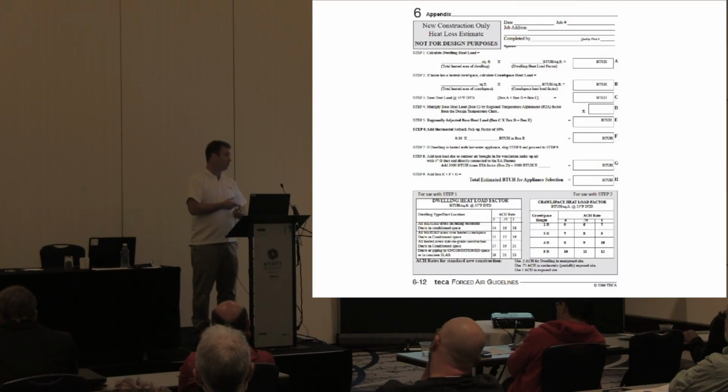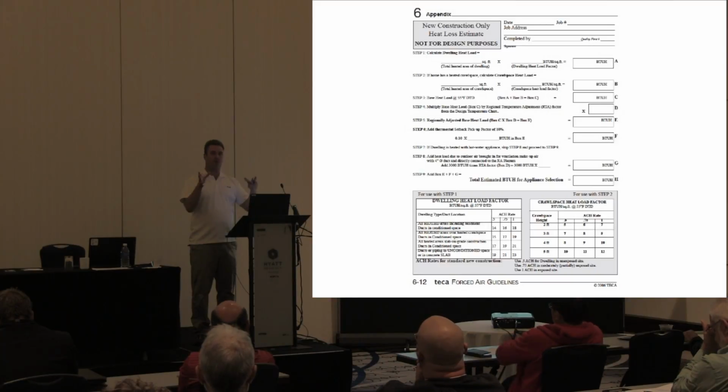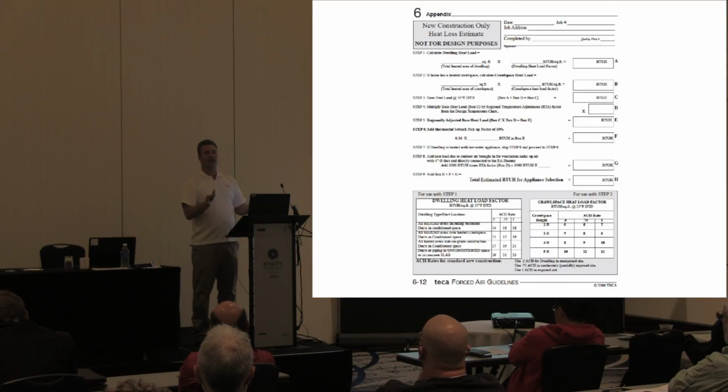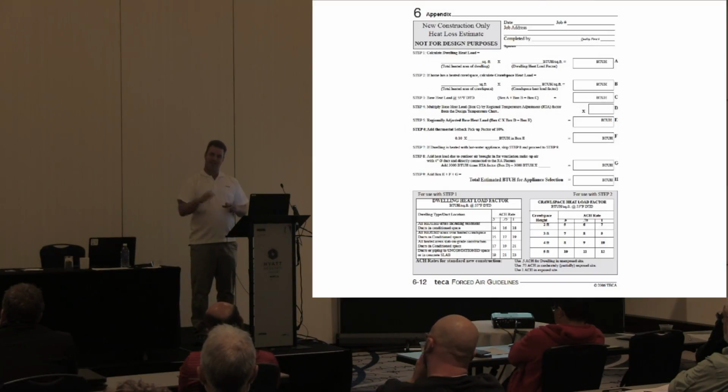So you usually have to put a zone system in, or put some separate system in for that room itself, a lot of times, when you get into those bigger high-end houses. And a lot of times once you go over a certain square footage, you're already looking at the possibility of putting in 2 heating systems anyway, because of the square footage and the limitation on how big a furnace or heat pump you can buy. So the easiest thing to do is to eliminate the room that has the biggest skew off to the side of all the other rooms.